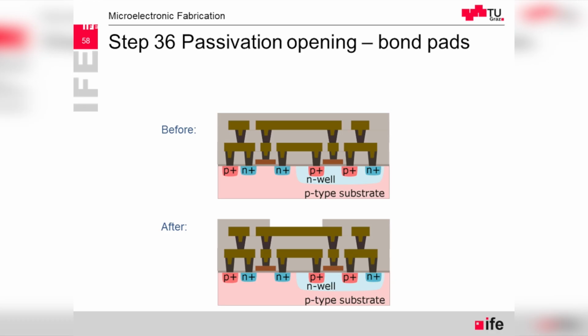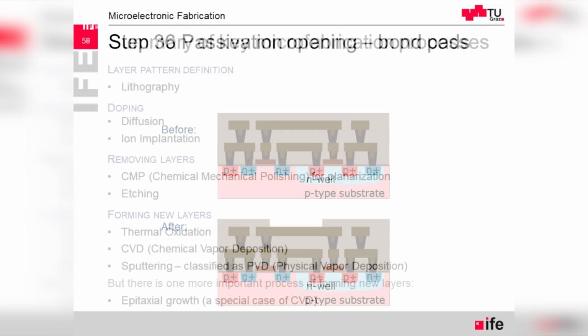It's even difficult to find all the details about the recipes of how it's done, but what we know is that it's a very complex process, so gate forming and with applying appropriate stress on the channel in order to influence the mobility of the charge carriers. So that is also part of the process steps that have to be involved. And then not to mention that many materials that are used, also chemical reactions, they are constantly being improved, like the photoresist itself. There is the whole science behind in order to also improve the photolithography.